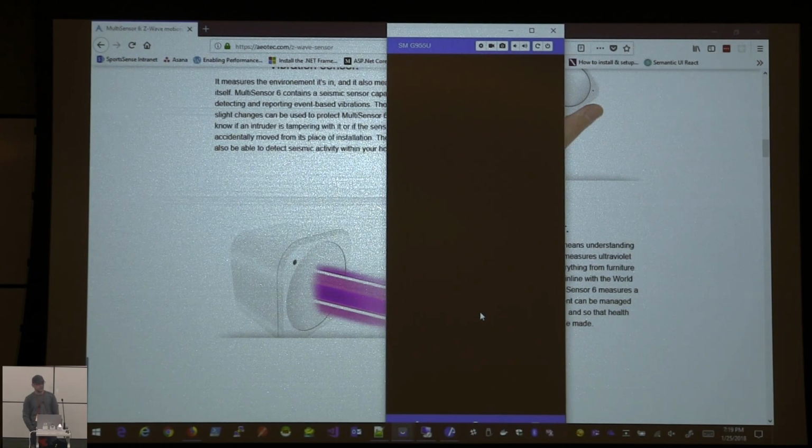For instance, for the Linear garage door opener, to reset that to factory, I couldn't find documentation on it anywhere. So I just started pushing buttons and playing with it, because I'd learned on several other devices that some you hold the button for 20 seconds, some you push the button 3 times. There are different handshakes to reset different devices. I learned through trial and error that you have to push the button 4 times and then hold it on the 5th time for 5 seconds, and then it will factory reset. I got stupid lucky that I was able to even figure that out.